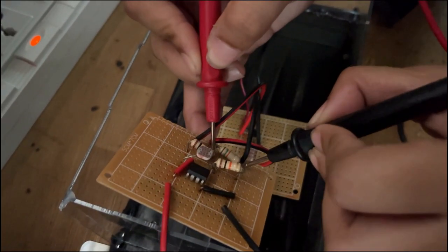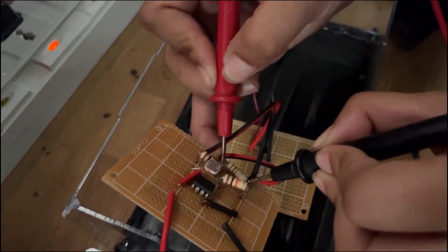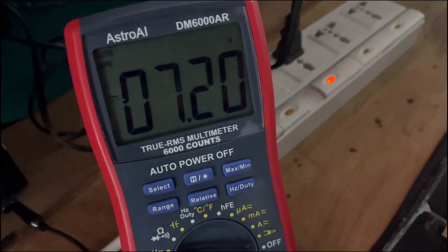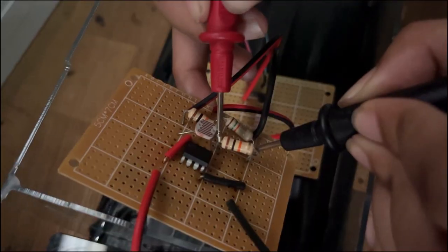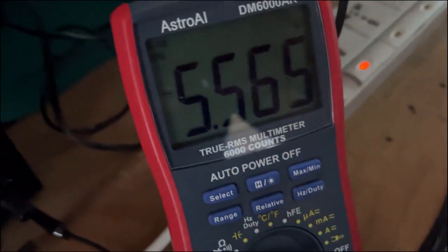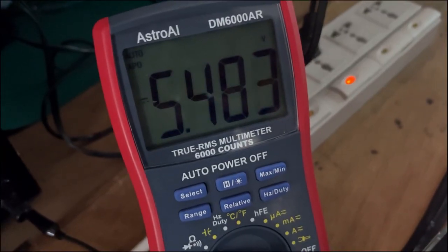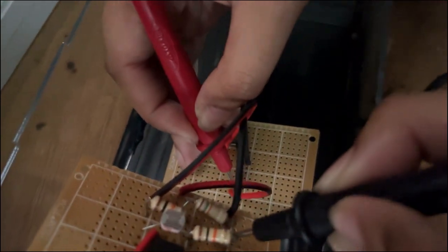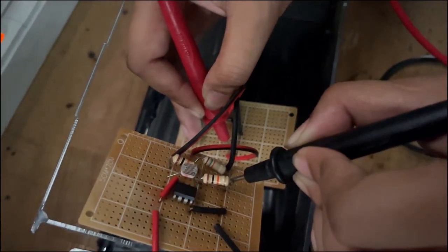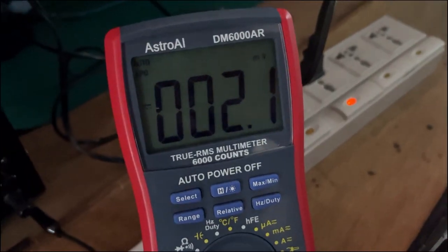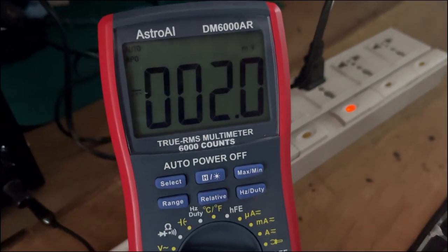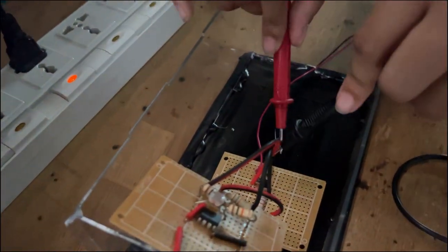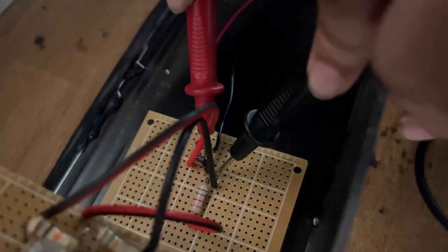In the video, we can see the actual values of the induced voltages across the circuit. First, we have the reference voltage, which is 7.21 volts. And the non-inverting input is 5.58 volts, meaning that the comparator circuit is turned off because it is not exposed to light, effectively leading to an output voltage of only 2.1 millivolts, in which case the BJT should also be turned off.